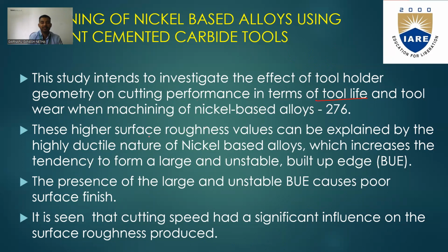The higher surface roughness values can be explained by the highly ductile nature of nickel alloys, which increases the tendency to form a large unstable built-up edge. The presence of a large unstable built-up edge causes poor surface finish. It is seen that cutting speed had a significant influence on the surface roughness produced.